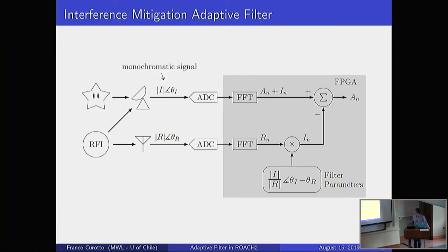If you multiply these two values in the complex domain, almost by cancellation, you get your original interference signal, and then you can do your perfect cancellation. So that's the justification. But the problem you're trying to solve is exactly how to compute these parameters as accurately as possible.